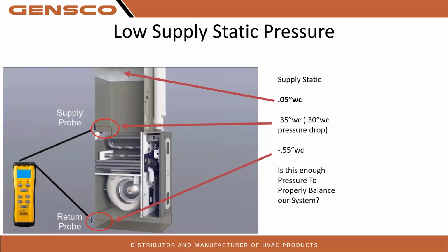What's going to happen to the sprinklers at the far end of that line when there's not enough volume, not enough pressure to get there? They're just going to kind of piddle out of the end, not much, right? Same thing when we talk about balancing a home. When you get a home that's got those extremity rooms that just don't seem to heat properly and don't seem to cool properly, perfect.